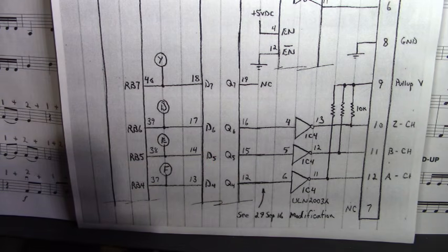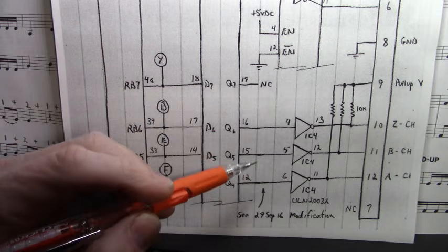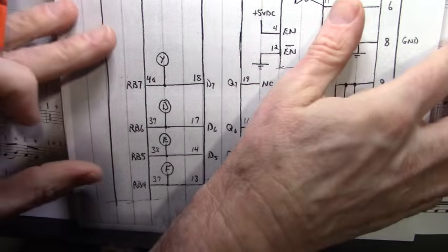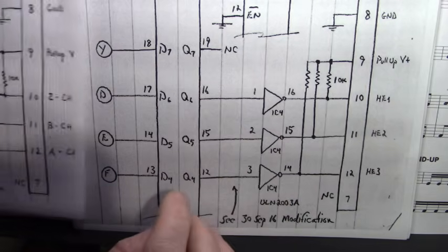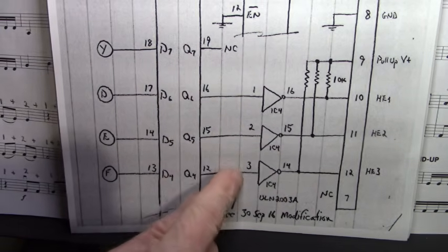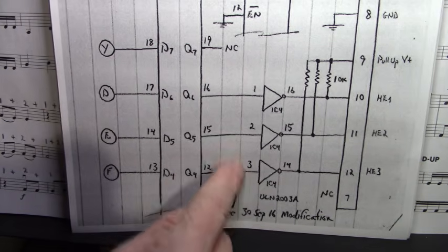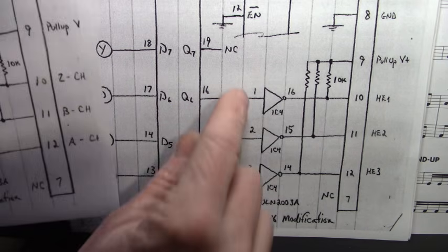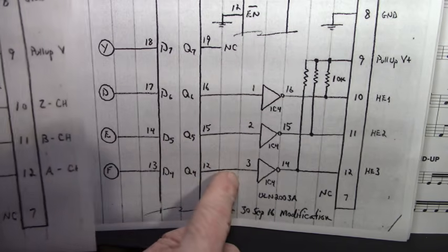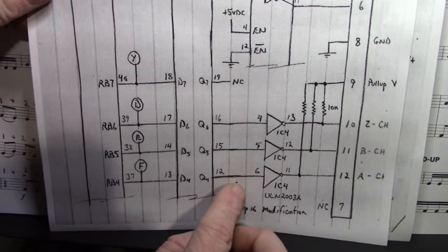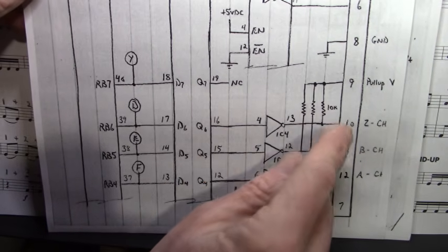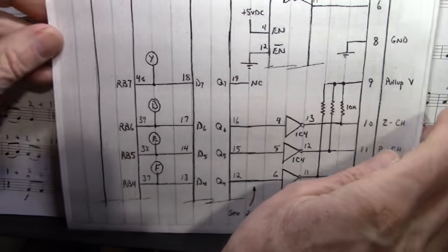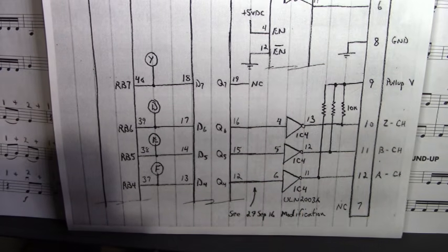And just to keep in step with everything, we had these three channels right here inverted with a 7414. I'll show you that when we get to that modification page. And I also did it with these Hall effects, just keeping in step so that everything was the same. I modified this point right here by adding the 7414 as well as this point right here, but mainly because I wanted the Z channel to go low to high on this open collector output of the ULN2003.